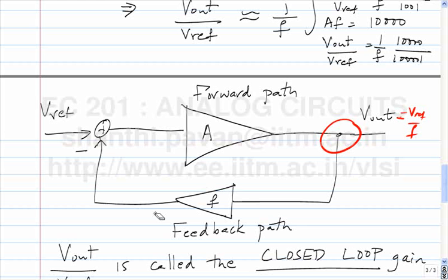For example, in the bias arrangements that we saw, we could dissect things and then interpret one as subtraction and one as the forward amplifier and so on. It takes some doing, and when you just look at a circuit, it becomes very difficult in a lot of cases to explicitly draw out the summation, the forward amplifier and the feedback part.